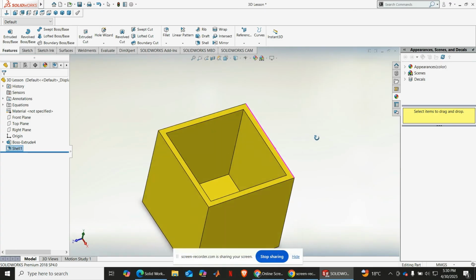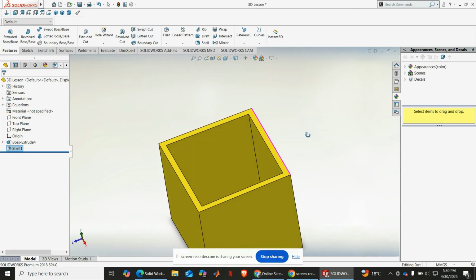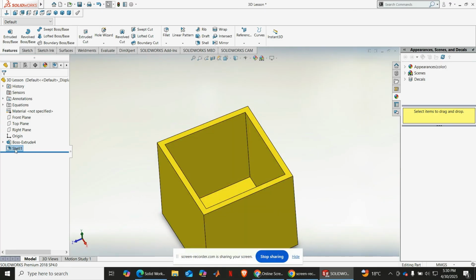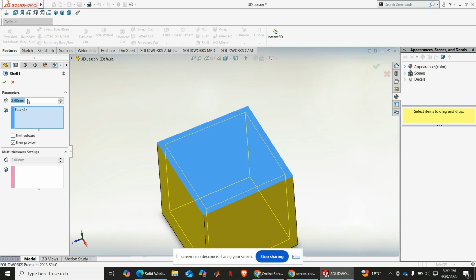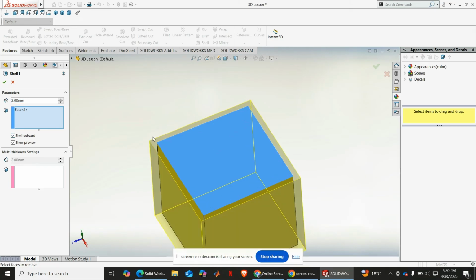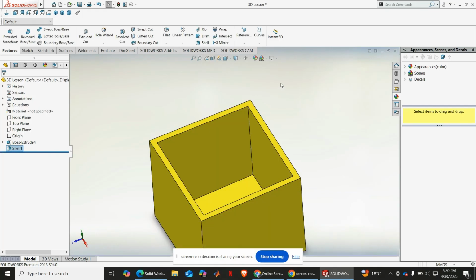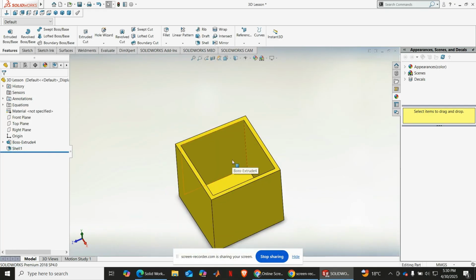It means everything left outward is what we dimensioned. So say here, edit feature, we said it's 2. But you can also shell outward. If you shell outward, then this box becomes the open surface, and it gives an extra thickness outward of the value that you set here, and then say check. Okay, so the surface that you choose, that's the direction of shelling.